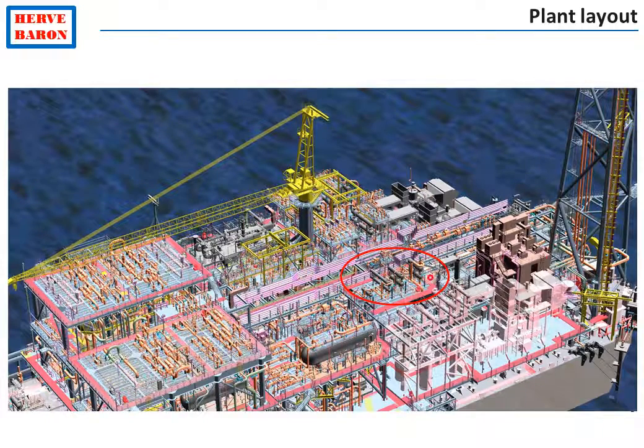Shell and tube heat exchangers are subject to frequent maintenance, which requires the removal of the tube bundle. Therefore, these heat exchangers have been located on the top level, on the top deck of this FPSO, in order to be accessible by the crane.